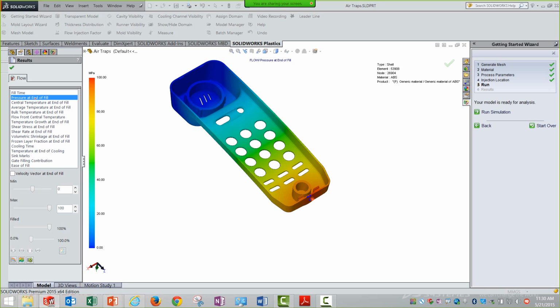while I am designing the part itself. I know the pressures are going quite high if the gate is at a certain location with a certain diameter. So what can I do? I can change the thickness. I can try different injection locations. I can try different plastic parts, come to a conclusion saying that okay, if I do these things, the part can be manufactured and this can be conveyed to the mold designer.